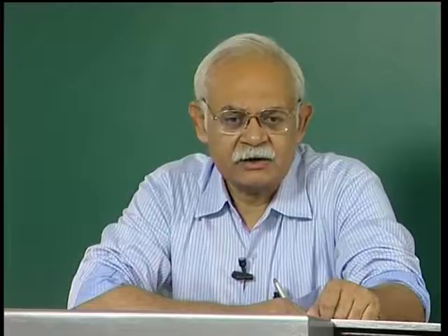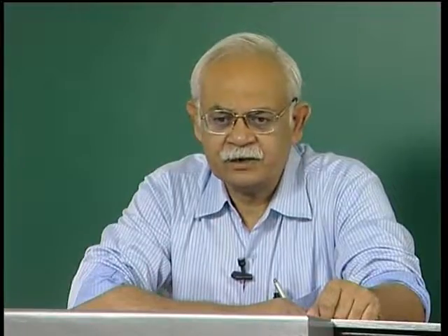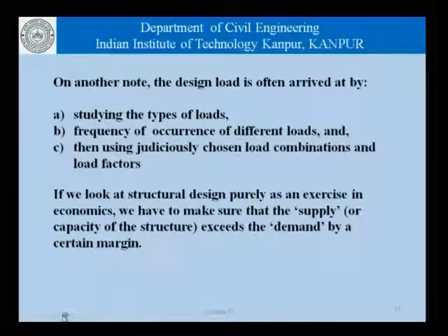That is also married to the concept of importance of the structure, the impact that its failure has. If a structure is a high impact structure, maybe a nuclear power plant or a very critical bridge, we might like that structure to withstand even those forces which are likely to occur very, very infrequently. Whereas if it's a structure which is not critical, we may design it for a lower level of loads or a different load combination.